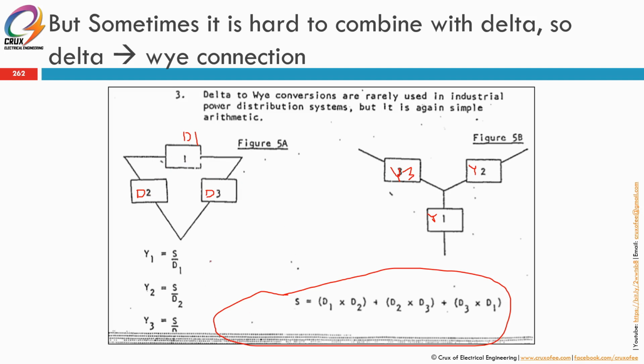So this is if you ever encounter it. When you draw and simplify the MVA, suddenly you find that there's a delta connection like this. So you must convert this to a star connection like this, so that you can sum up more easily. Alright.